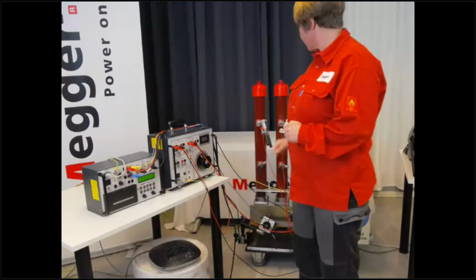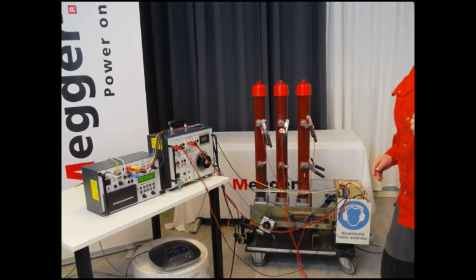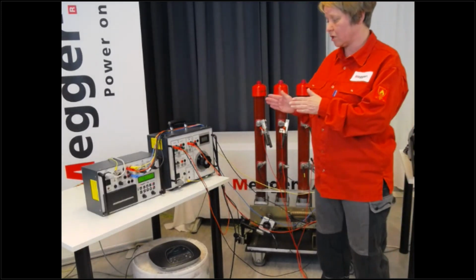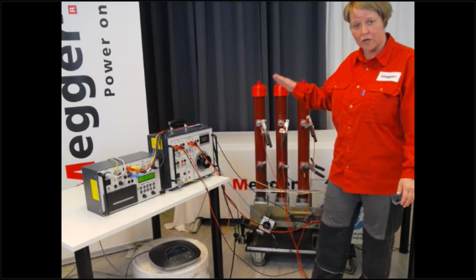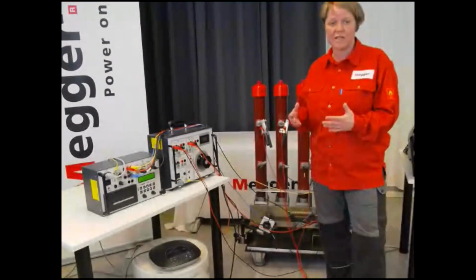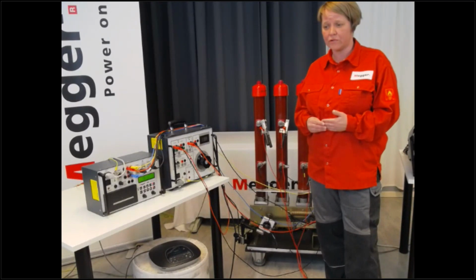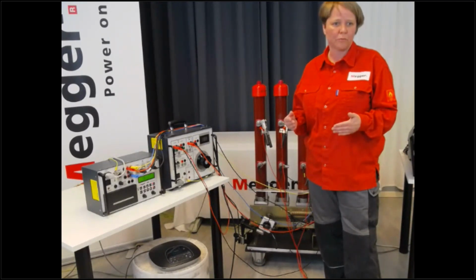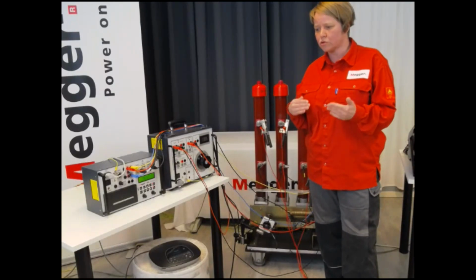So in 45 minutes, we're going to do a test with a TM1800. Then we're not going to do this kind of timing where you can only have one side grounded, but we're going to have both sides grounded, which is, of course, a very safe way to work when you work outside in the switchgear where you have capacitive coupling, induced currents, and this kind of thing. And also, of course, risk of coupling.